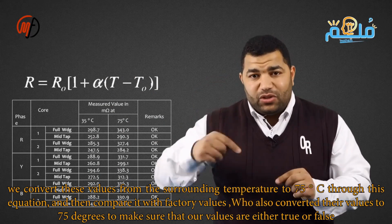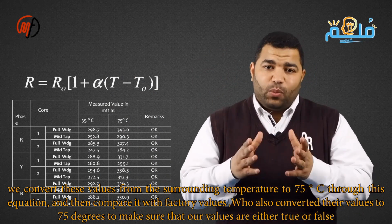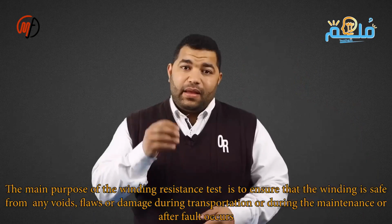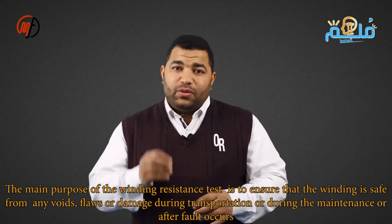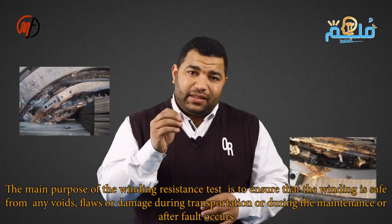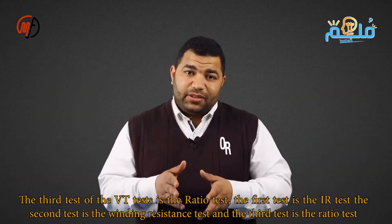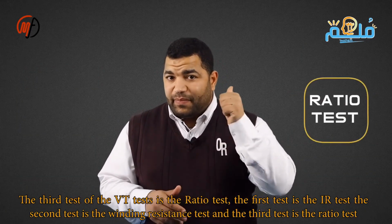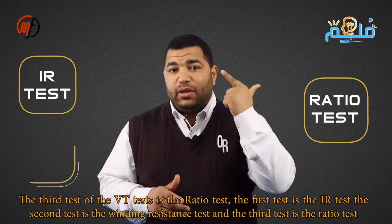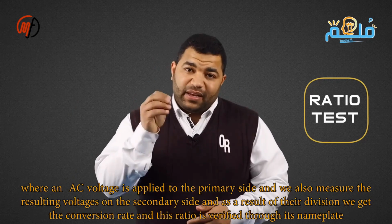The third voltage transformer test is the ratio test, after the IR and winding resistance tests. The winding resistance test checks the winding for issues. The third VT test is the ratio test. After the IR and winding resistance tests, we apply and measure AC voltage. Dividing gives the transformation ratio to verify.